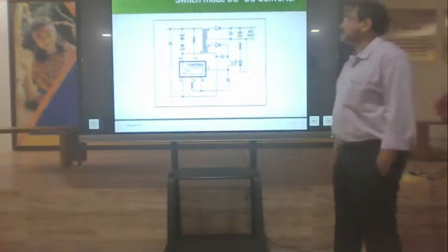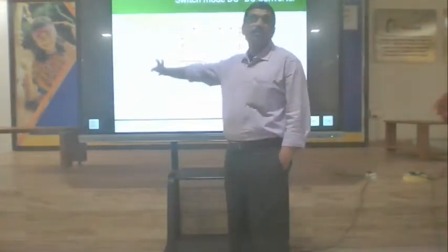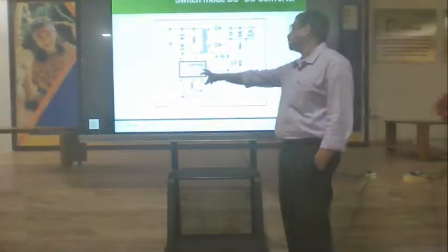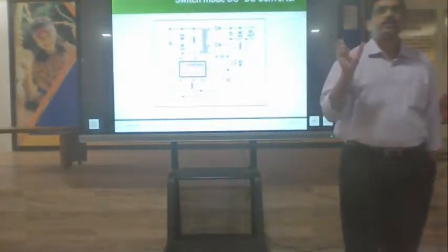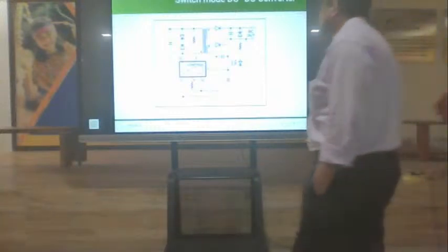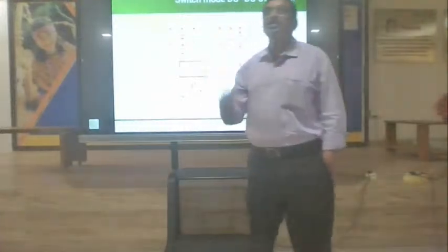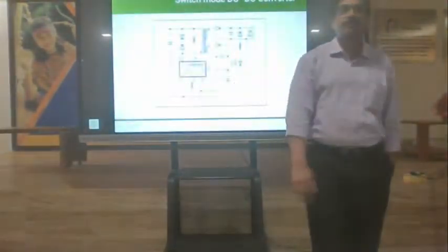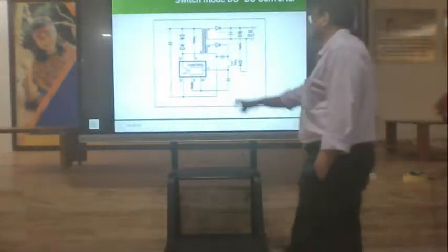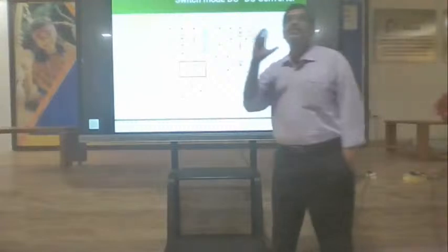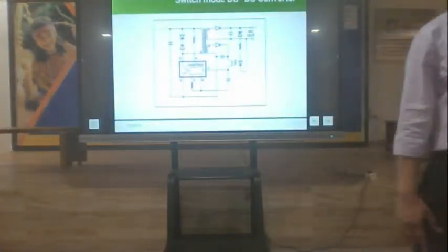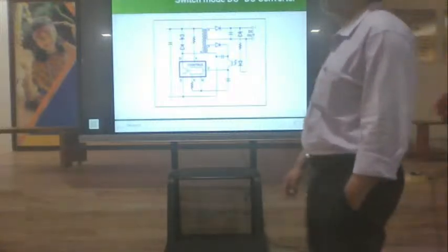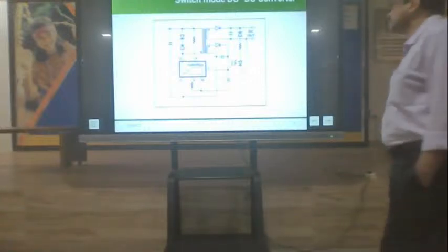Initially when you switch on the power, this controller will switch at a frequency that is set by the controller. Each switching circuit will have an oscillation frequency, and that frequency will depend upon the circuit you use. Let's say this is 100 hertz, 100 kilohertz, sorry. It will have intelligence, so it starts at a certain fixed frequency. It might be switching at 100 kilohertz with a duty cycle of 50%. Like full duty cycle is 50%, so the total on time is 50%.